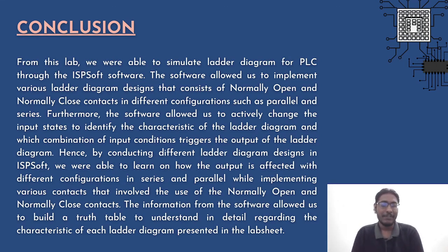Hence, by conducting different ladder diagram designs in the ISP Soft, we were able to learn how the output is affected with different configurations in series and parallel while implementing various contacts that involve the use of normally open and normally closed contacts. The information from the software allowed us to build a truth table to understand in detail the characteristic of each ladder diagram presented in the lab sheet.